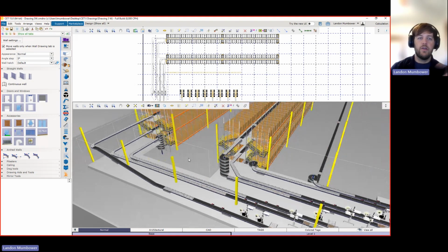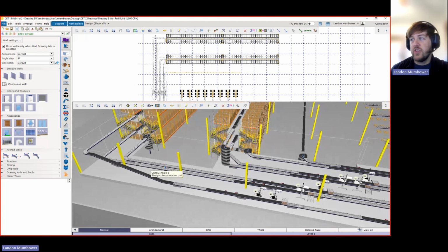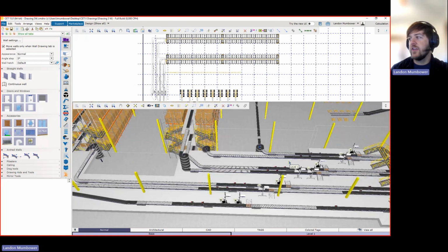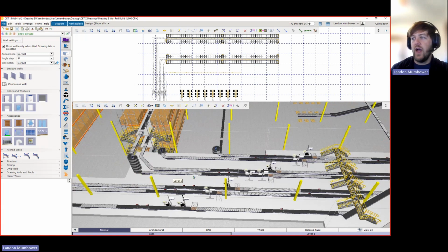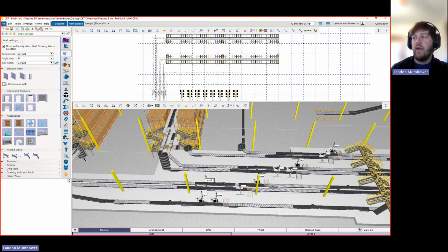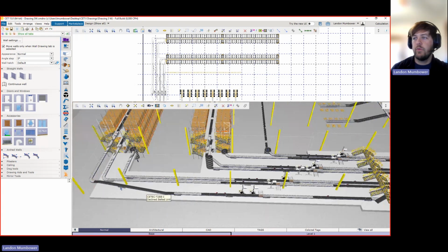Now, the note I'll say here is that while I'm using this to explain a point that you could show two options in your drawing, hey, we could do a spiral or we could do a decline conveyor. In reality, with this design, we actually have to do a spiral here because we do not have this distance to do a decline conveyor prior to the print and apply. So I know that on this section here, I have to come off the spiral, I have to gap, and then I have to scan, and then I can do my print and apply. I have that space here, but I don't have the space from here to this conveyor up here to put a decline in. And you can kind of see that difference here where we put the decline conveyor here. We have all this runway. We don't have that space here.